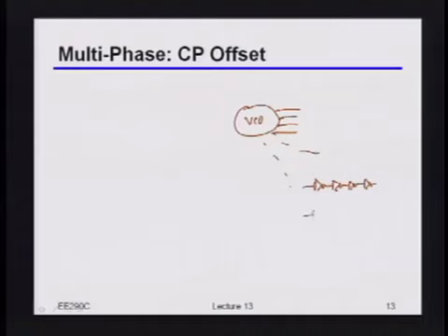So what they basically do is they say, well, okay, look, if I've got some VCO that's sitting inside of a PLL, well, if I can just somehow nominally move the phase of that VCO around, then basically, automatically, if I really have a multi-stage ring oscillator, so you should keep in mind that what's inside of here is just something that conceptually looks like a bunch of inverters tied back to back. Okay, and I guess I'll draw it so there really are 4 phases here. Right, so something that looks, say, like this.